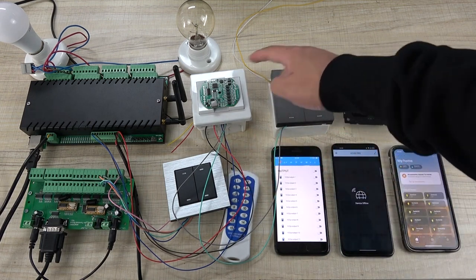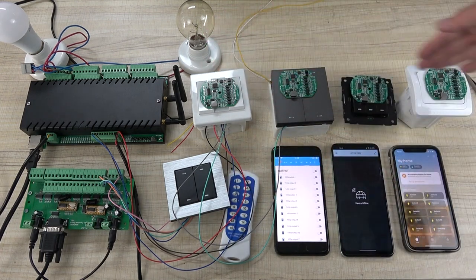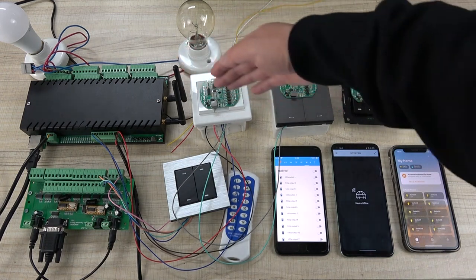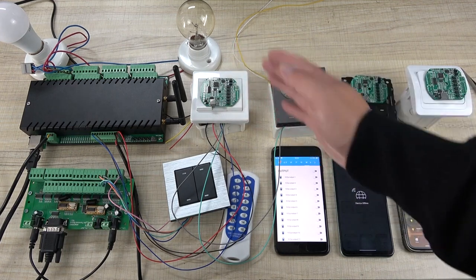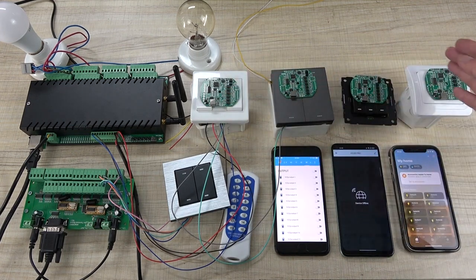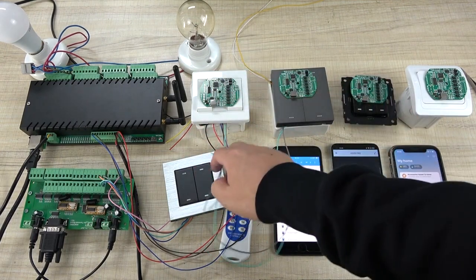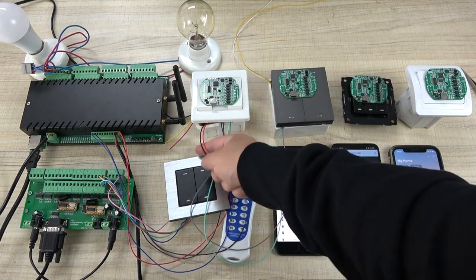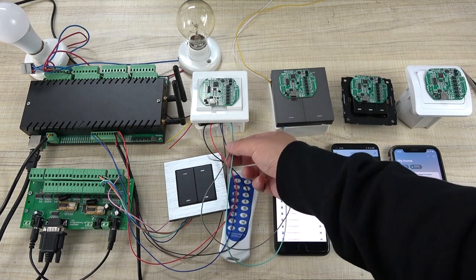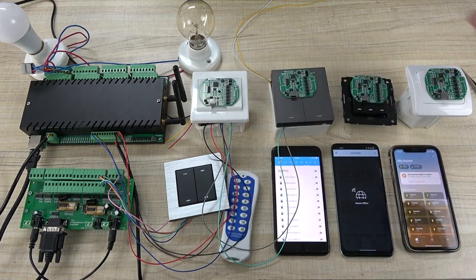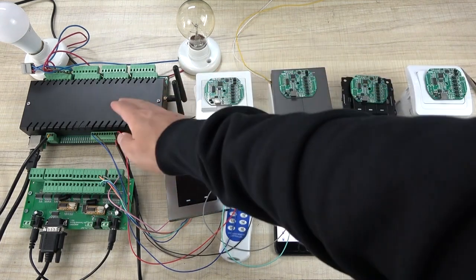And this is for the power. Just let all the cables and all the switches share the DC 12 volt power. That will be the power supply for this board. So there are almost 4 lines: 12 volt, ground, and the RS485 communication. So this is the bus line to connect with this H32B Pro.